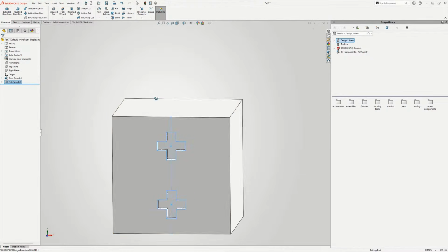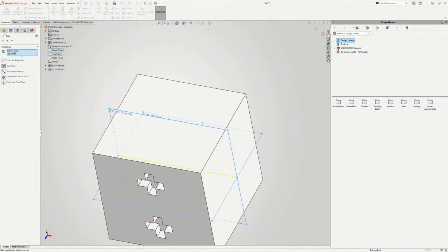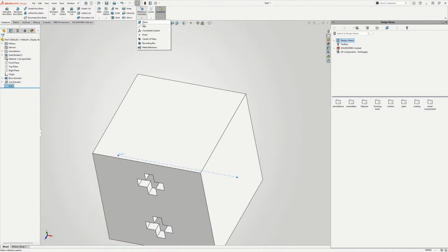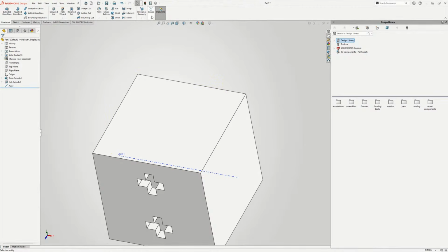So now I could, of course, just create these sketches again, but instead we are going to create some axes for us. Okay. And because now I want to rotate them all instead. So go here and create one more. Oh, that was the plane.